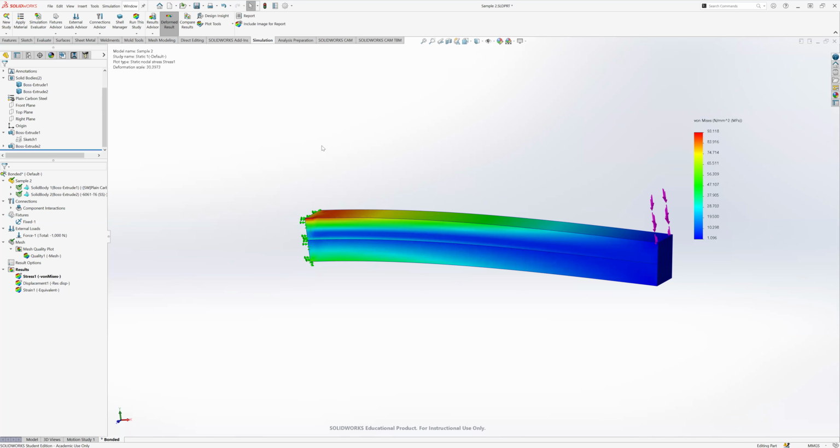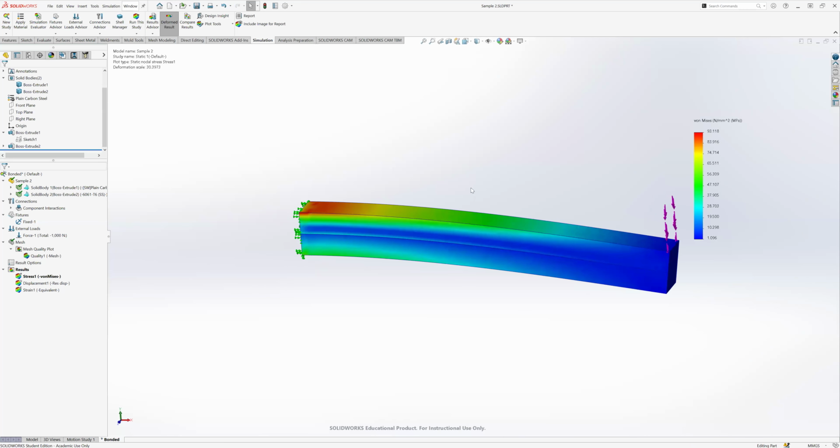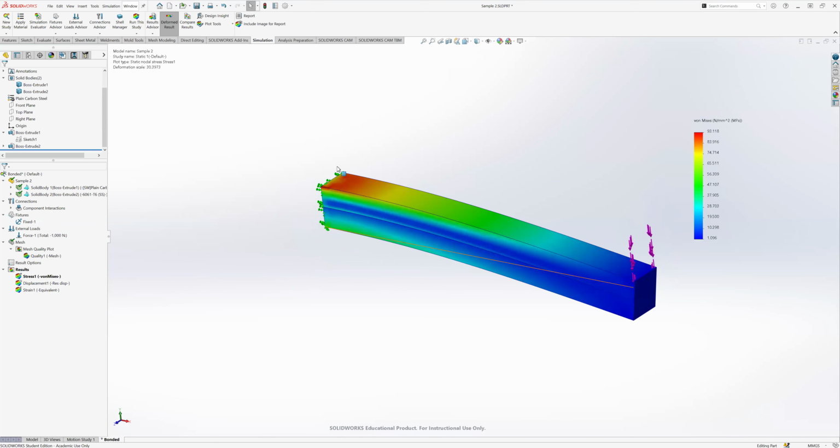So that's another thing when you're dealing with composites. These are metals, which are a little bit easier than dealing with polymers. But that's something to look at, because you may run a hand calculation, and if you remember from strength of materials, there is a method, especially with stuff like this, where you can convert one material into the other by adjusting the cross section. You can look that up online if you're dealing with a composite beam or any composite. So that is pretty much a bonded boundary condition, or bonded component interaction, bonded connection. Any questions about this study so far?